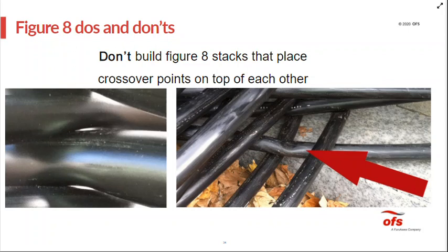And last slide on figure eights. I've seen crews make very neat figure eight stacks. They were very proud of them and they look very pretty. Unfortunately, all the crossover points were stacked up directly right on top of one another. And what happens is that all that weight has to be carried by the bottom layers of cable. And so you end up getting very high compressive loads on the bottom layers of cable.